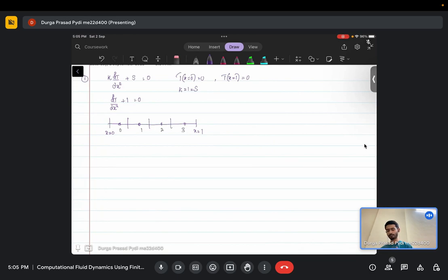So this particular kind of discretization will ensure that your boundaries lie on the face, where the face centers will be lying on the boundaries. Alternatively, you can choose this as your cell centroid, and this is your first face.